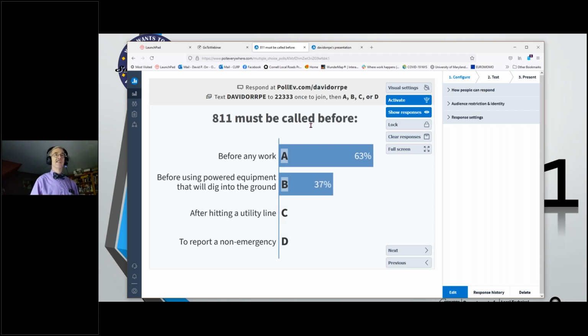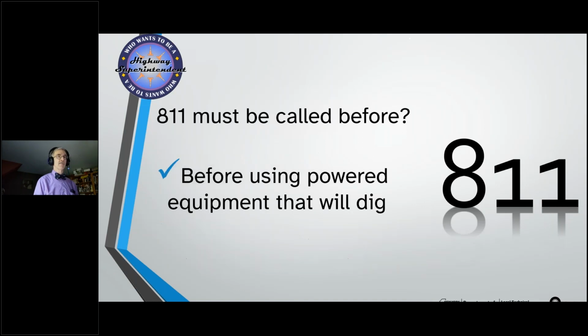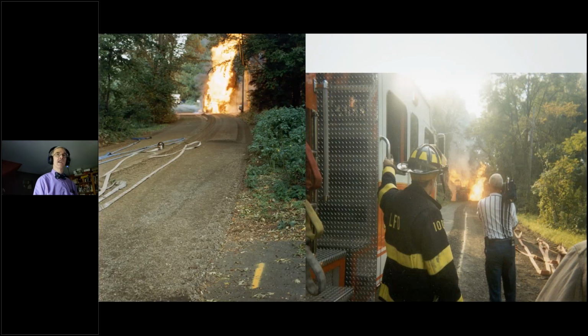What do I think? If you're not sure, call. Most of the time, you're better off to call, because you don't want to take that risk that somebody finds out the hard way that something happened that you didn't want to have happen. So know the rules within your own state and follow them as much as you possibly can, okay? In New York State, it would be before powered equipment. But yeah, in Ohio, it would be before you dig. But technically, it's anytime you're more than 12 inches. But this is why I'm like, please just call.